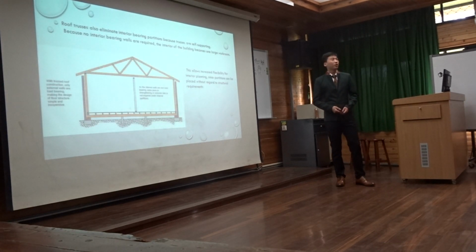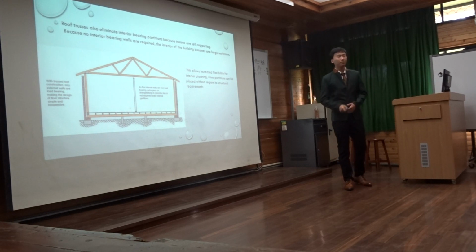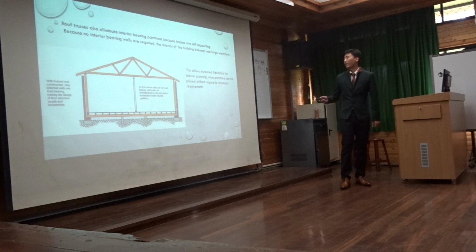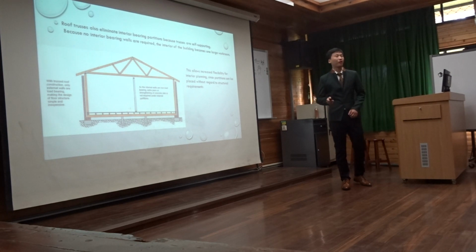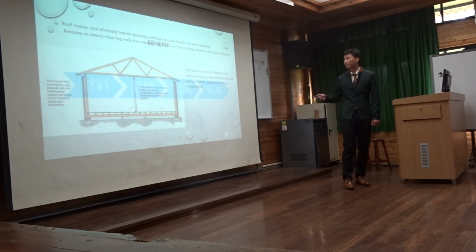Roof trusses also eliminate interior bearing partitions because trusses are self-supporting. If no interior bearing walls are required, the interior of the building becomes a large workroom. This allows increased flexibility for interior planning, since partitions can be placed without regard to structural requirements.